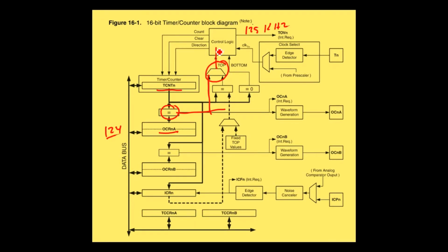That signal goes into the control logic, which sets the clear to set the counter back to 0, and this cycle will just repeat in the hardware without us messing around in software. It'll count up for a millisecond, it'll clear, it'll count up, it'll clear. And we'll also turn on an interrupt, so every time we hit that top and do that clear, we're going to generate an interrupt. And that interrupt will just update a counter to essentially count the number of milliseconds since we started up.